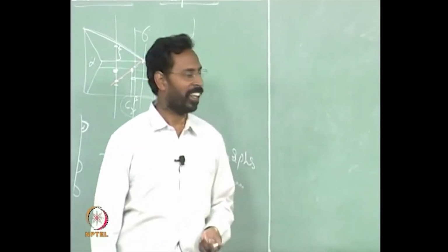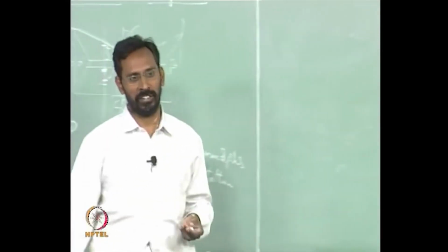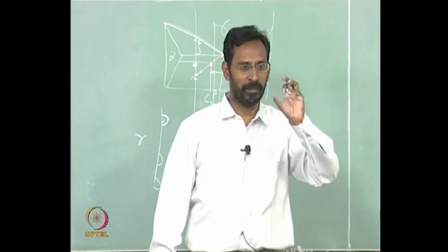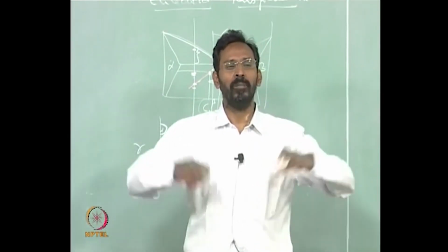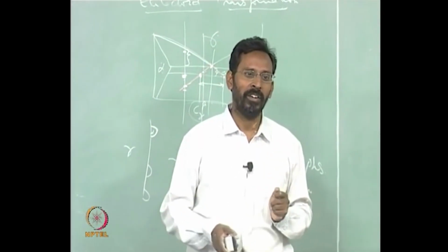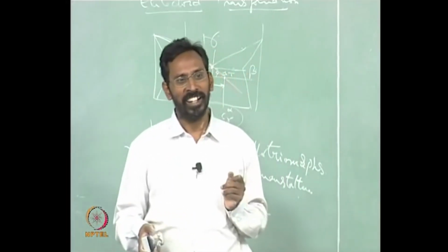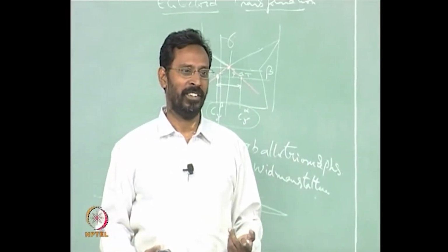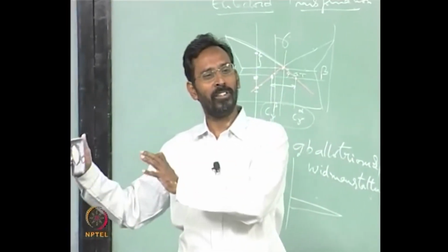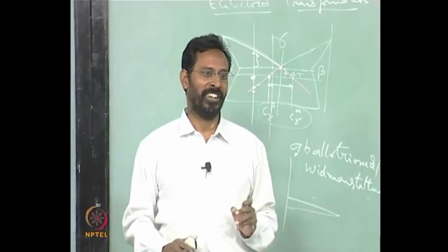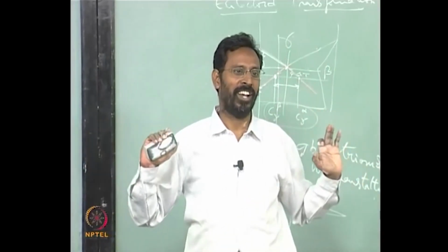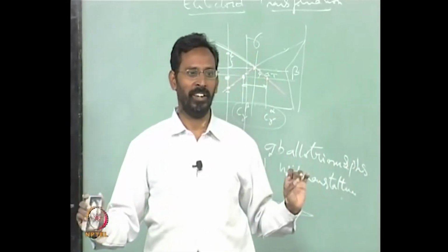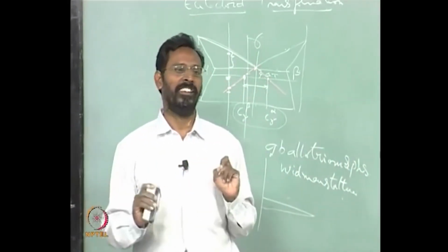In fact, if that is the case, the cementite forms in a eutectic reaction where cementite is coming out first and the remaining liquid is becoming gamma, can I call this eutectic? Because both of them are not forming at the same time. So ultimately you have to see the final microstructure, liquid giving 2 solids finally. So if you look at it, the gamma gives 2 solids finally, one is ferrite, another is this one.